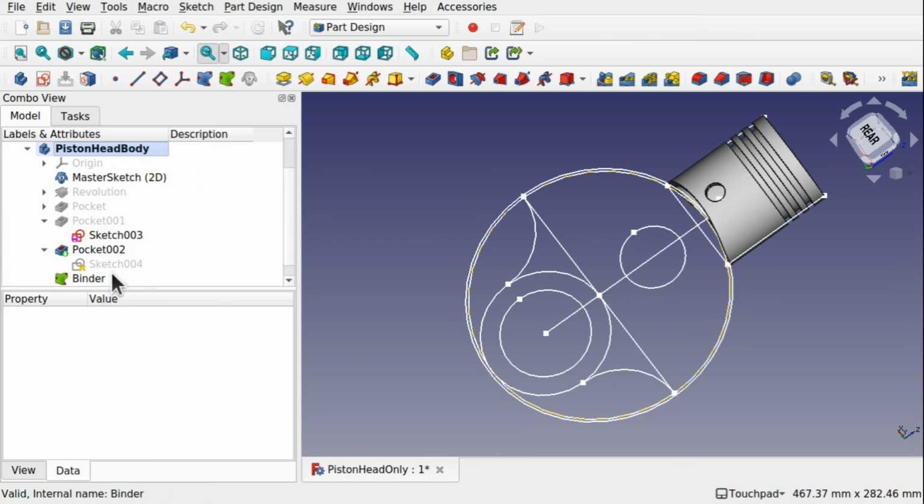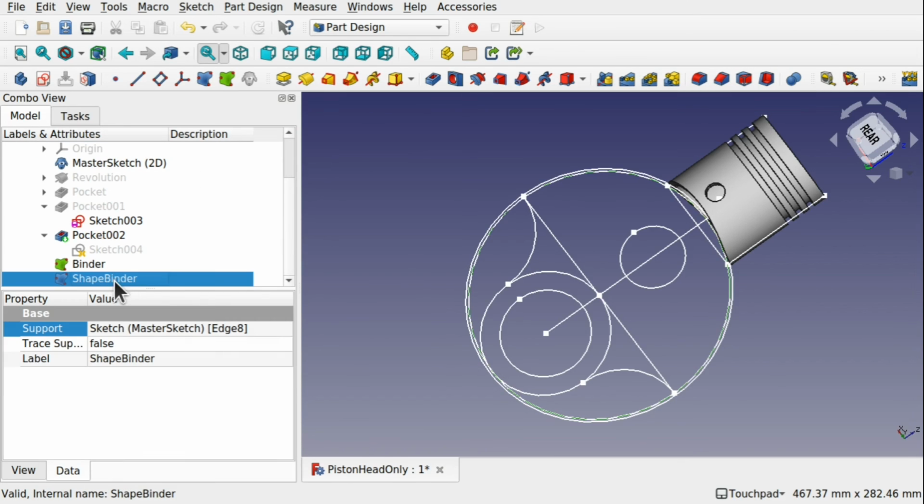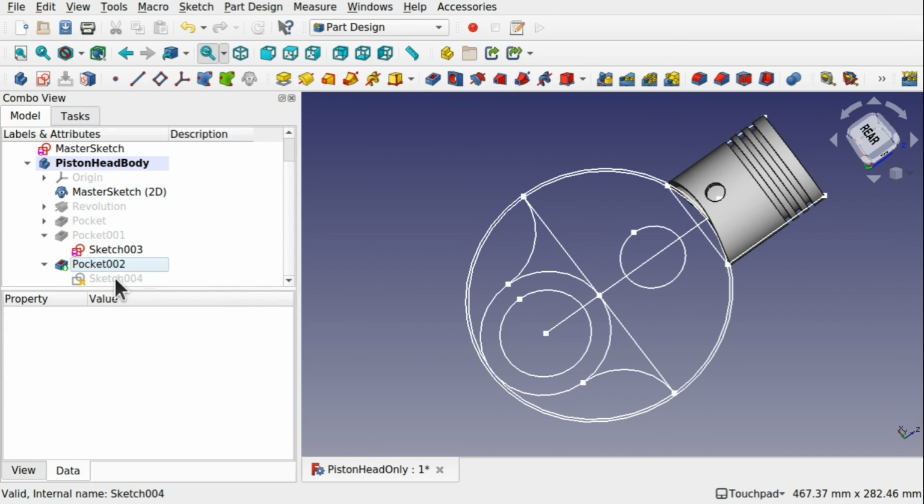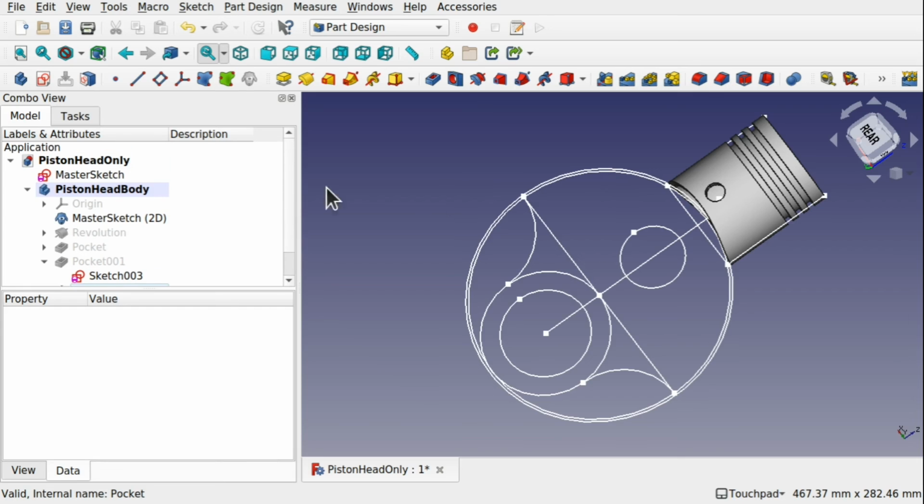Okay, shape binder, as you can see, there is very limited capabilities of that shape binder for actual movement, let alone being able to change the scale of it. So this is the reason why I prefer clones over shape binders, in that you have the scale in there. It's up to personal preference if you want to use a shape binder, but it gives you that extra level of configuration, of customizability in there to change that.